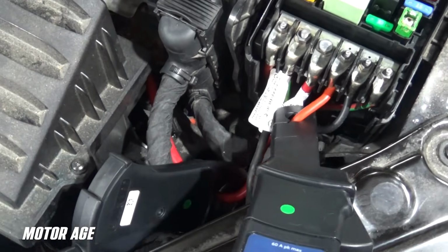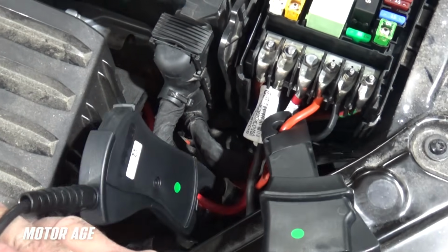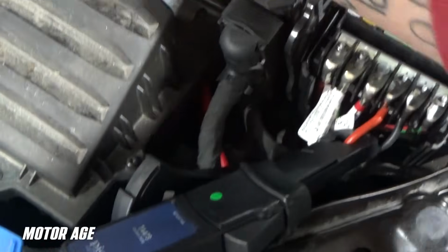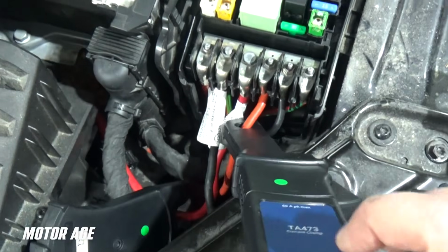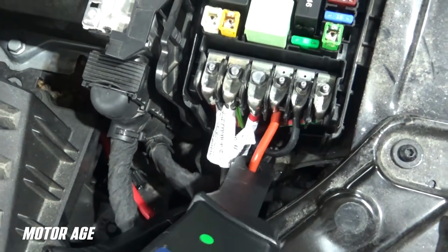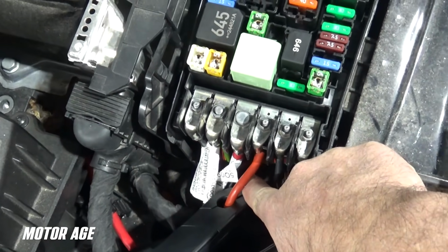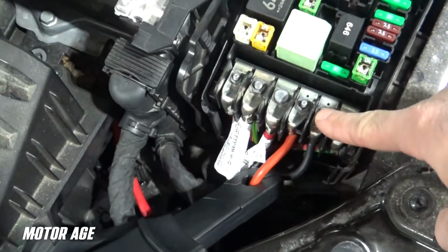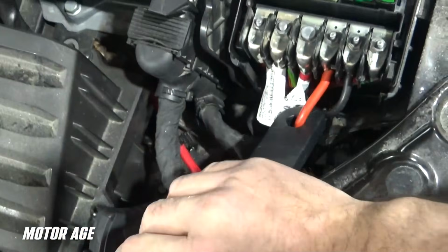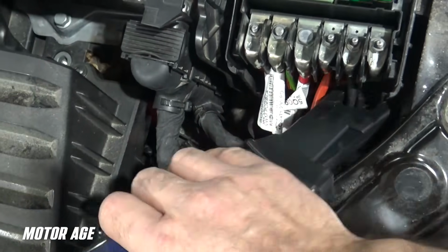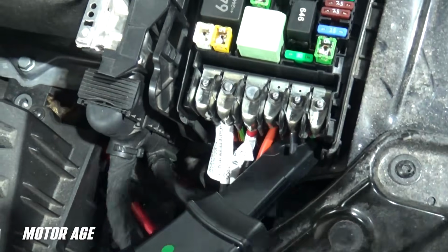So I call this the wheel of misfortune. We've got our high amp probe, our primary amp probe leaving the battery as our trigger, our indicator that a problem is present. And our first capture yielded us no current flow in this circuit here. So we're just going to try one of the other ones. And this black one right here looks like a nice candidate. It's right next door, easy to get to. I'll move my amp probe there. And we are going to repeat the process.